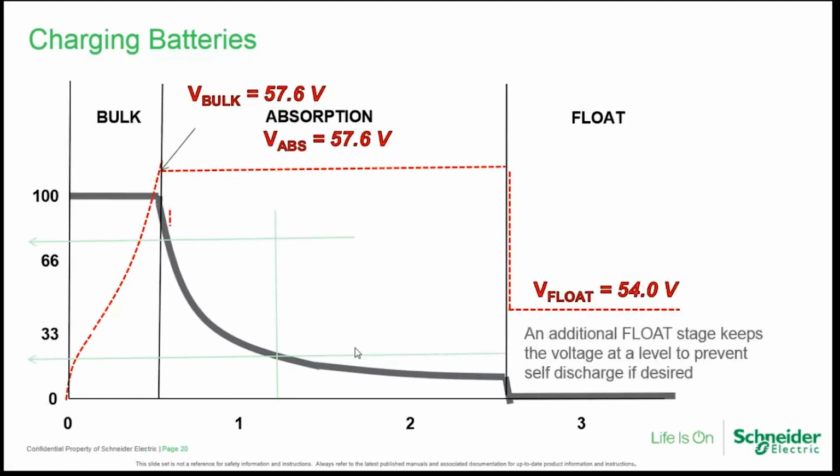Optionally, if we enable something called a float stage, we set it at this lower voltage here, and that prevents the battery from discharging. Doesn't actually charge it, but prevents it from discharging. Some lithium batteries don't like this.